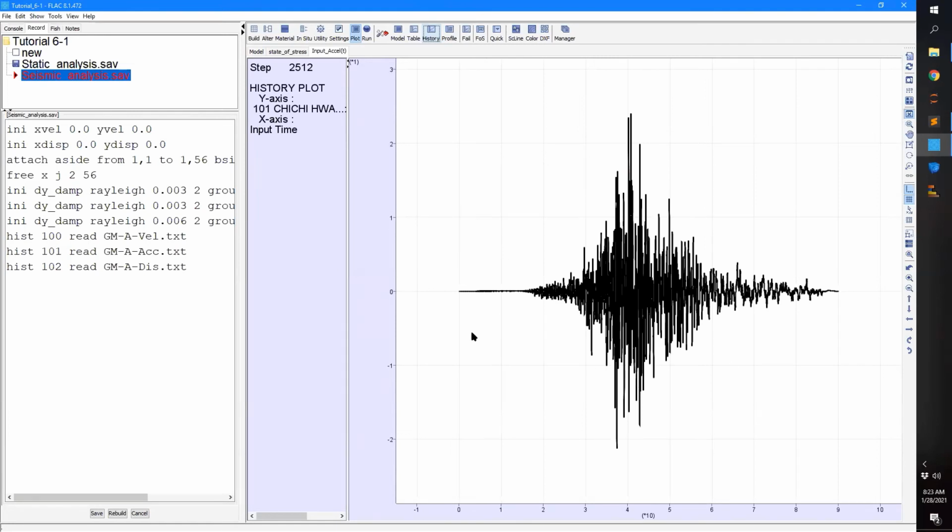See that the time history is 90 seconds long. It has a peak ground acceleration of, let's see, what is that? It's 2.24, so 2.2, so 0.2, no, just a little bit up. So basically 0.25 g, but it has a fairly long duration. Okay, so we have that.